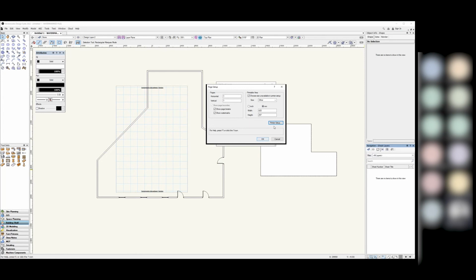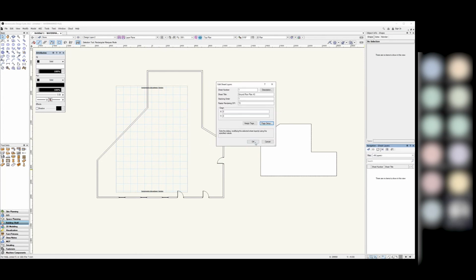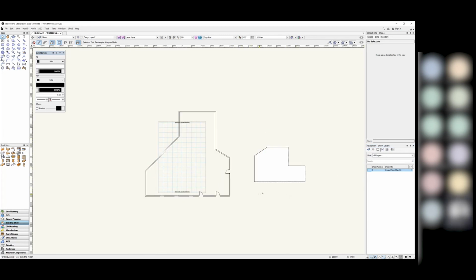That's a bit better. So I went to printer setup that time, set it to landscape, click OK. Maybe set the DPI a bit higher, set that to 300 dots per inch, just because it's going to be printed out. It doesn't let you preview it by default. We're still looking at the design layer for now, but we do have an empty blank page defined now.